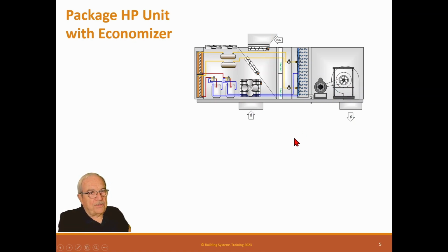So you'd have to pressurize the space enough to push it out of this relief damper, which normally blows the doors open. I mean, it doesn't blow them all the way open, but it blows them open an inch or two, and we start discharging air outside, and you see it all the time when you go in a store.